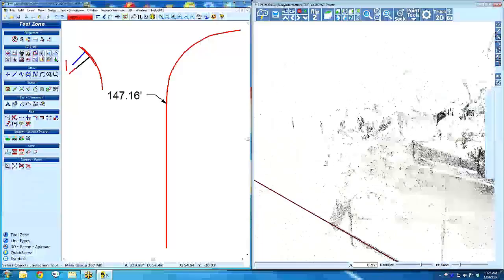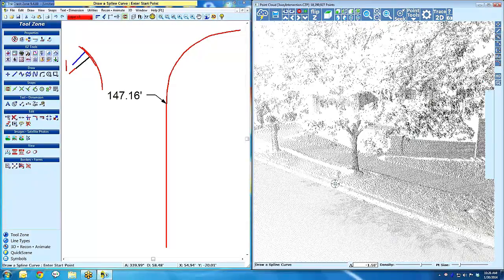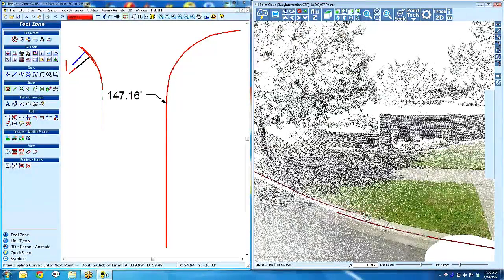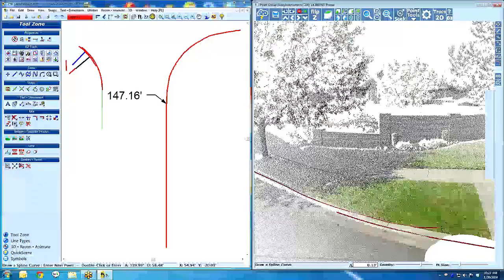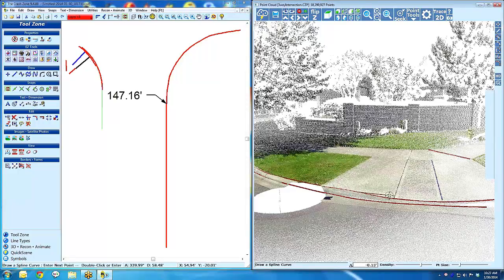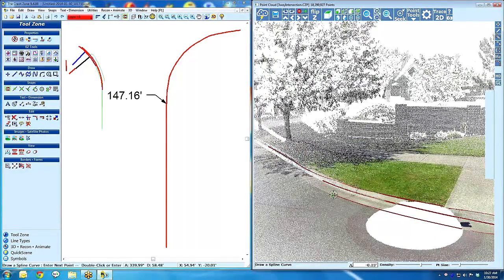And just a little quick note, if you were zoomed in, like say right here, and you were clicking to draw, and you don't have enough screen but you want to keep drawing, you can't click your mouse to navigate because you're in the middle of drawing. If you hold down your control key, then you can navigate. You can pan and then start clicking again. You can hold down the control key and rotate, move around. So the control key just gives you access to moving around in here, and then I'll hold down the control key again. I could just use my mouse to navigate again without slowing me down.